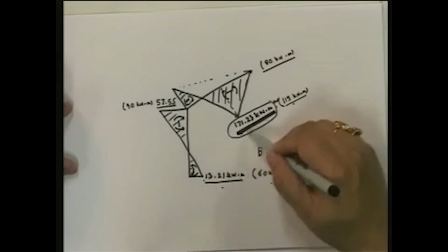There's a tremendous amount of bending moment variability, and that essentially implies that curvature goes up, and you might have cracking problems, etc., if you have reinforced concrete. So by and large, increasing restraints in the structure is a good idea, as long as you don't keep increasing it to a point at which displacement goes down and almost the entire forces are transmitted.